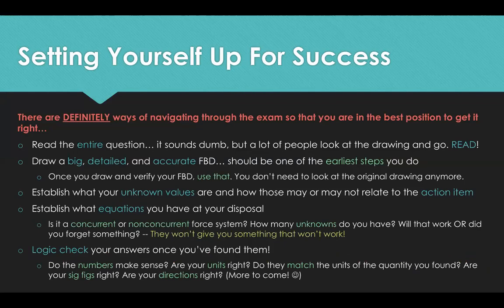So step one, please read the question, because with all the frames problems, they could either be asking you for pin reactions or internal forces, and that would totally change the approach of the problem. Problems can look the same and ask for something entirely different. You should absolutely read the problem before you even draw anything.